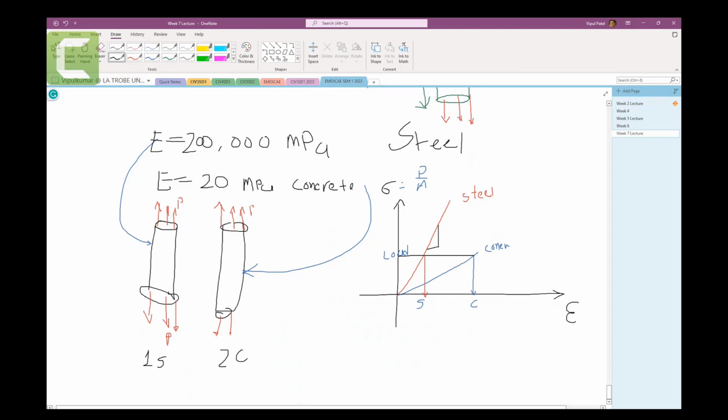So that is a rise over run, like the stress. If you take this part, which is the stress, the difference from this point to this one, and the difference from this point to this point, and you draw it, that stress over strain gives me the Young modulus. Young modulus is equal to stress over strain, the ratio. Let's say this is sigma 2 and sigma 1. You can take the difference of these and the difference of these.